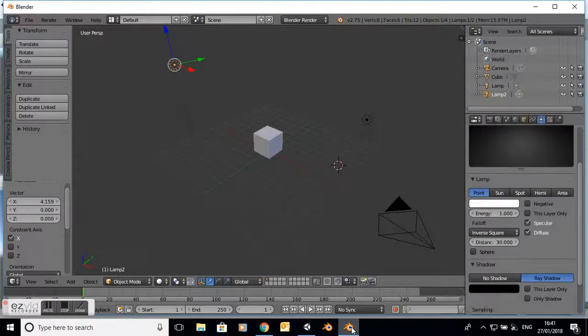Now this is Blender. It's a 3D modeling application which creates meshes. So this is our basic default mesh, which is a simple cube. And this is going to form the basis of our tray. Now the first thing, of course, it's a bit cubey. We want it to be more trayy. So I want to expand the directions in this way. So that's the x-axis, and this one, which is the y-axis.